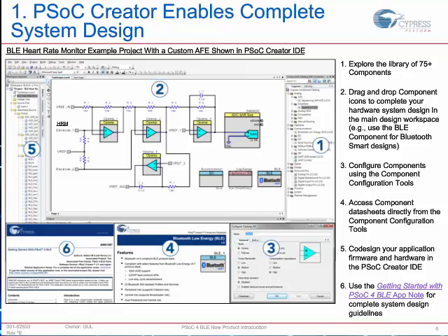Once you've done the hardware configuration of a specific PSoC chip and defined the hardware in the way you want your system to work, the tool then generates a set of APIs for each of those components that you have on your schematic. And then you can go into your traditional firmware development, which is getting into the code editor and writing embedded C code in your main.c file that the CPU would execute.